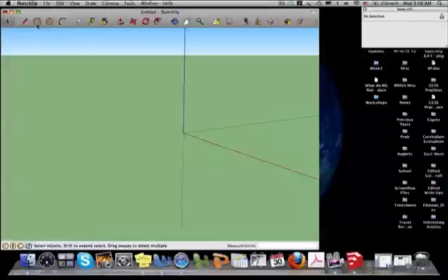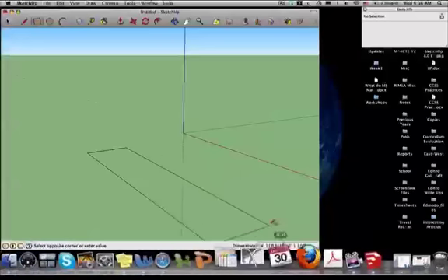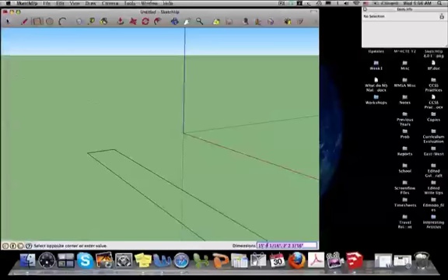So I'd like to show you how to make a rectangle that has exact specifications in terms of things like length and width. So I'm going to start somewhere, it doesn't matter where. I select a point, and I just pull out my rectangle a little bit there. Now let's say I want to make a house that is 25 feet long by 40 feet wide. If I go down to this dimensions box, right now it's telling me what the length and width of this rectangle are. My length is right now 15 feet, 9 1/16 inches. My width is 2 feet, 2 1/16 inches.